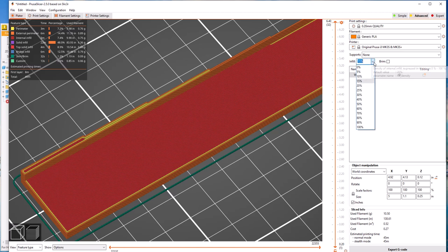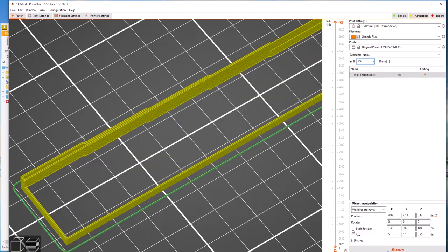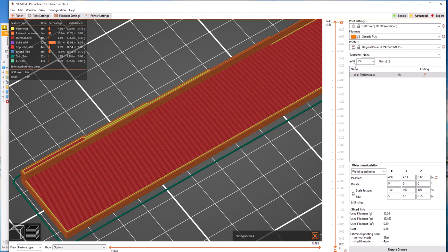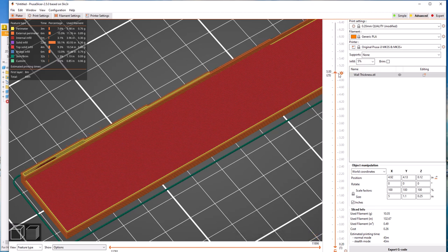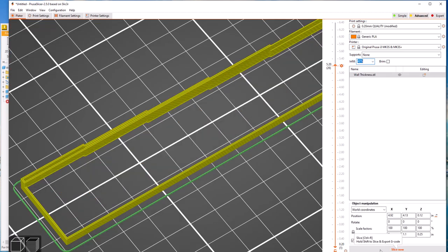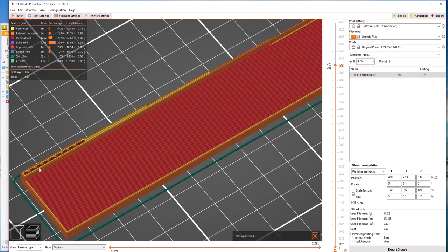If I change my infill to 5%, let's say, which is that one, I'm going to scroll down a little bit maybe. There we go. So that's our infill, and it's pretty much putting no infill in there. If we go to 15%, it's putting a little bit in there, it's fine. We can go heavy and make it really heavy in there if we want to, 40%. But that's just filling space in a wall.